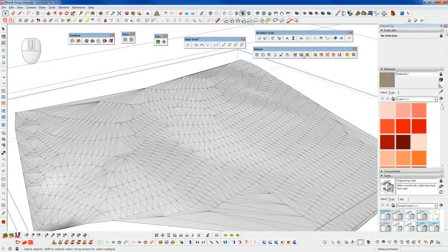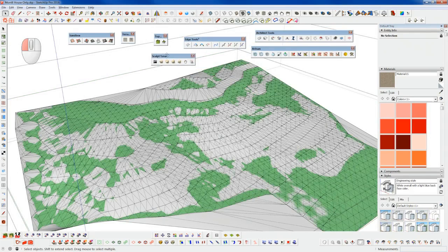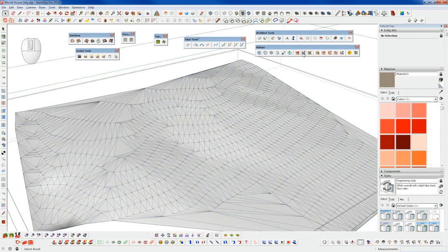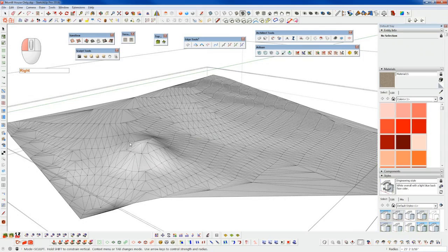And if we wanted to use a sculpting tool like Artisan, which is the paid plugin, or there's also the free sculpting tools here, which is called Sculpt Tools from BTM, and that's a free plugin that you can download for sculpting. It has a lot of the same sculpting features as Artisan, but Artisan is a lot more robust in what it does, and it gives you a lot more visual control over what you're sculpting. So I'm just going to use Artisan here for the sake of demonstration.